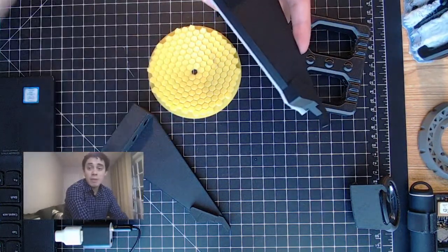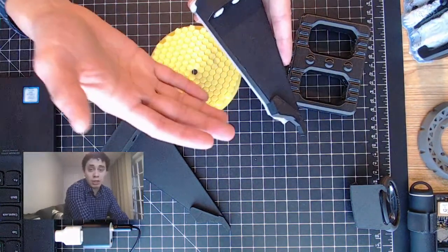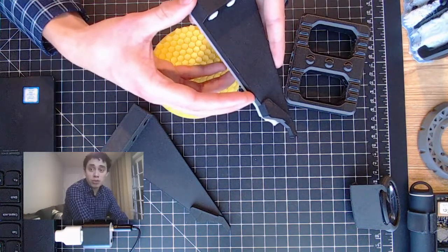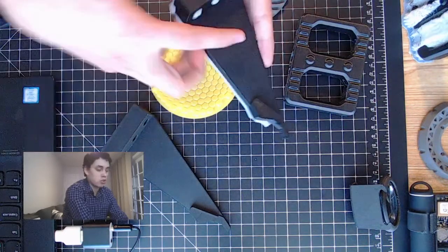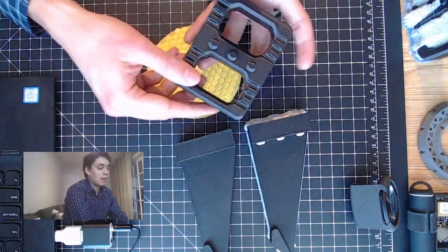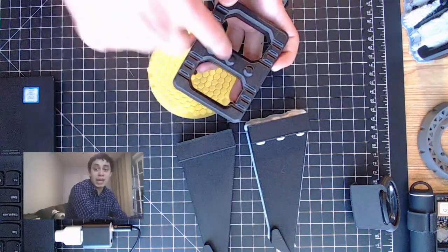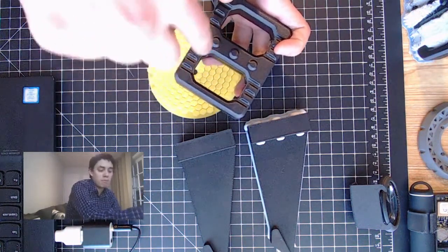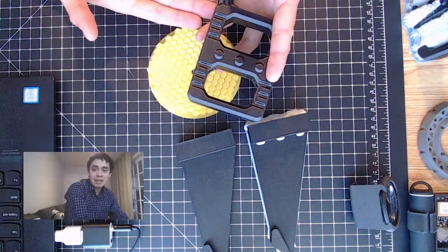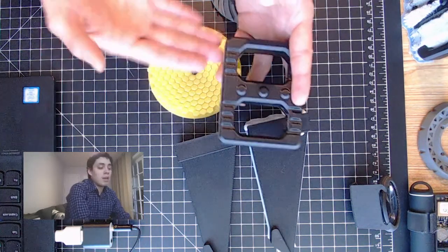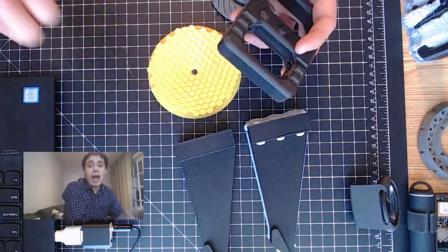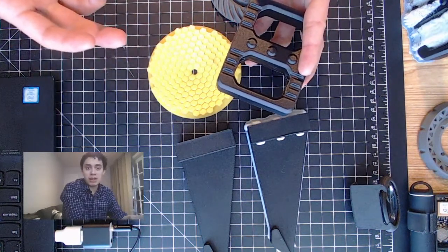But in any case, the first consideration when printing a part and orienting it is: is it going to withstand a considerable amount of force? And if so, where is that force coming from? In the pedal example, it's a clean way to look at it. My force, most of the time, 90% of it, will be coming from the top down. Therefore, I should probably consider having my layers flat against the build plate, which would make them perpendicular to the force being applied.